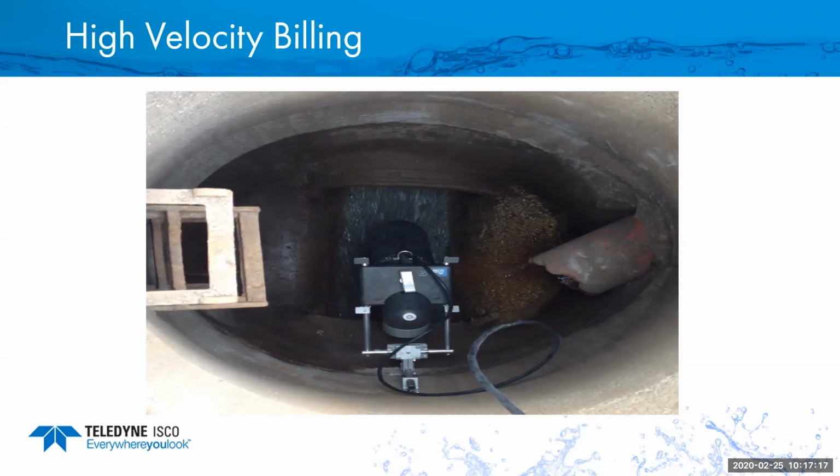The Y-axis, which is the 45-degree angle, you need that for the accurate velocity measurement. If you don't get it perfectly installed or it changes a little bit, the laser will mathematically compensate based on that accelerometer. The laser can be mounted either pointing into the flow or away from the flow. We don't care which direction you mount it. It can also measure bidirectional flow or velocity.